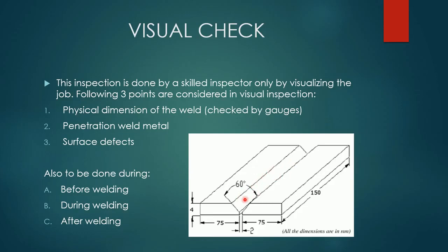Now next, during the welding. Now welding process parameters, welding consumables, preheat, interpass temperatures, placement of weld run, distortion control, heating temperature and time, etc. These different things are checked during the welding. How many number of passes are going to be done? After each and every pass, we have to clean the welding. That kind of things are considered in this second step.